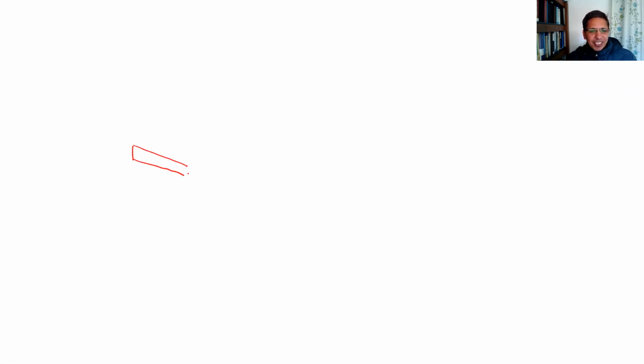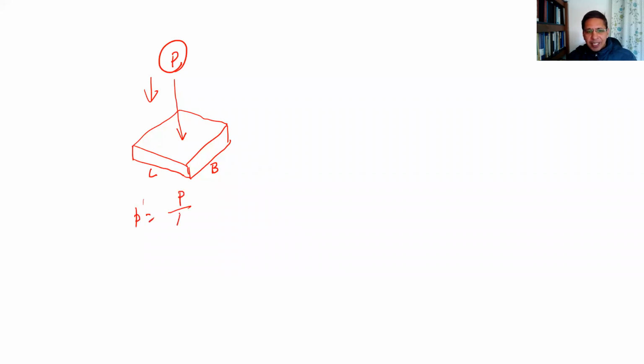If it was square footing, right? Let's say square footing first. You see? It is like this, right? Footing is square footing. So if there is a load given onto this, that means area would be L times B, isn't it? Given load P, the pressure from the external load would be, let's say, pressure equals what? P, the total load, divided by area, isn't it? So that means P divided by L times B. Do you understand if it was square?